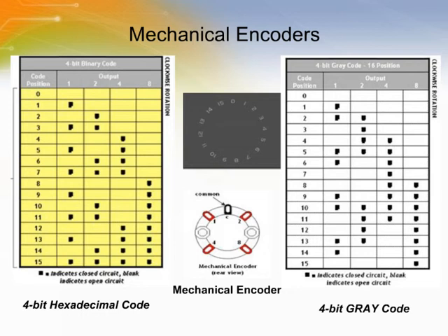If the first 10 positions are used, the encoder is set to output BCD code. These encoders are also available in codes called octal complement, BCD complement, or hexadecimal complement. As the mechanical encoder shaft is rotated from one position to the next, the encoder will momentarily generate some of the other output codes before it comes to rest in the detent position of the desired output code.